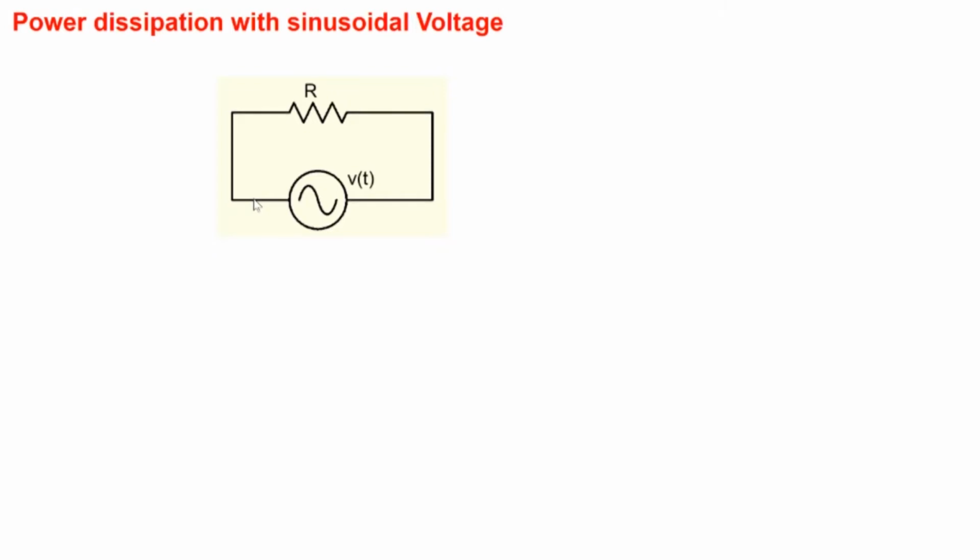All right, coming back to, so we've seen voltages and currents, how to calculate that. Let's look at power dissipation. So we know that if I take a voltage source and connect it to a resistor, the power in the resistor is V squared by R, so v(t) squared by R here. And most of the time we are not interested in the instantaneous value of power. What we want to know is the average power dissipated. So when we talk about average, we take this as a continuous signal, and we take an average in the form of 1 over T, integral from 0 to T, of v squared by R times dt here. We do the averaging by performing this integral.